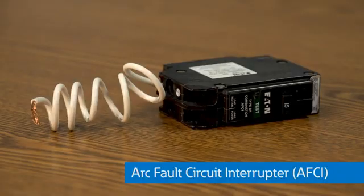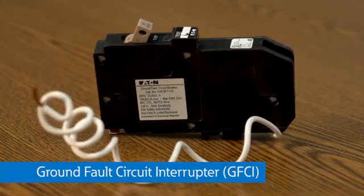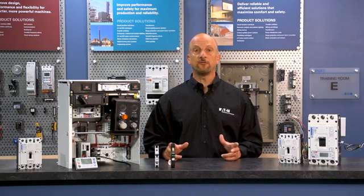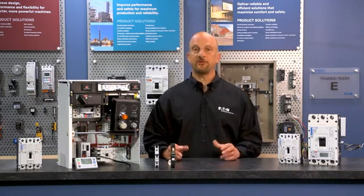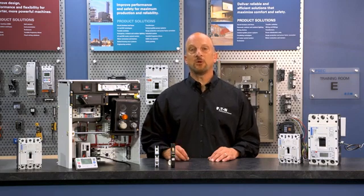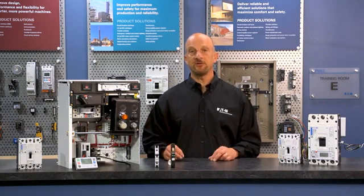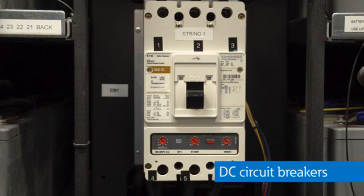Arc fault circuit interrupters, or AFCIs, and ground fault circuit interrupters, or GFCIs, are typically plug-on miniature circuit breakers that offer arcing fault protection and ground fault protection in residential applications. The NEC requires almost every circuit in new residential applications to either have AFCI, GFCI, or both protections on every circuit in a home. Another special application for breakers is DC circuit protection. DC circuit breakers are specially designed to break DC currents, which is more difficult to break than AC current, since DC doesn't have the zero crossings like AC.